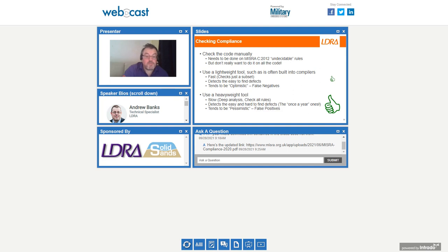There we are. You can use a heavier weight tool. These tend to be slower, much deeper analysis, and they check all the rules. Yes, they detect the easy stuff you found before, but they'll also find the much harder to find. But they can sometimes be a little pessimistic, and you may get false positives. But my view is it's better to have a false positive that you can check than a false negative that you don't know about.